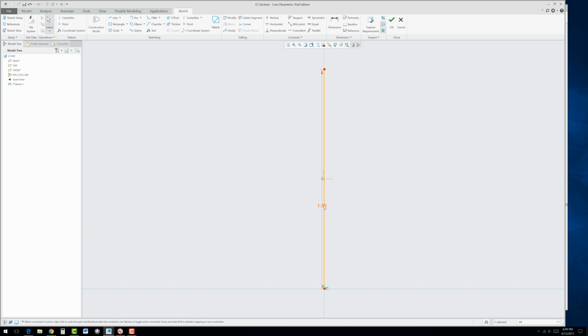Alright, so with that now we're to scale, and we're going to go ahead and find the arc tools and go with center and ends. Move your pointer and float it directly above the vertex of that line and click. Drag it down to connect to the vertex. Click again and drag it around. And we saw this tool back in exercise 4, so it's a good review for you there.